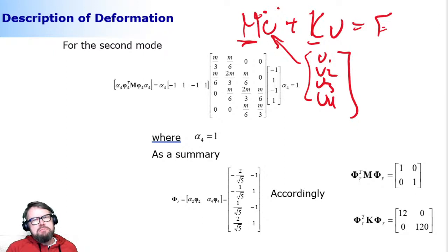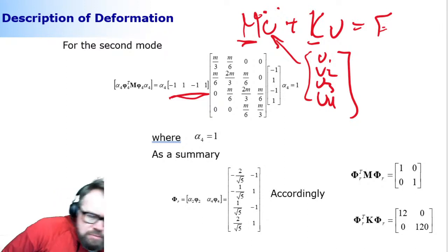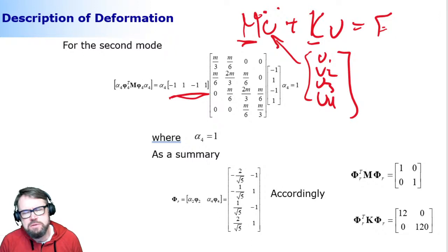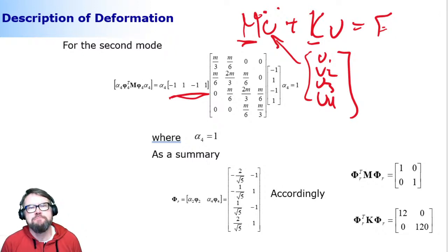But anyway, just to give you a demonstration, I'm using 2 deformation modes, the ID number 2 and ID number 4. Why not ID number 1? ID number 1 I want to skip here because it was representing the rigid body motion, and I don't want to deal with that here because that will be accounted for by using the body reference coordinate system. And why not number 3? Yeah, that's a good question, but I just decided to skip it because I want to reduce my model.